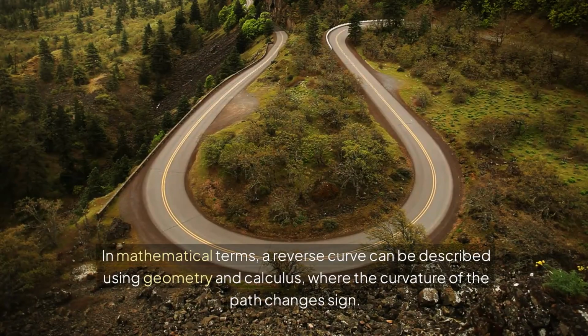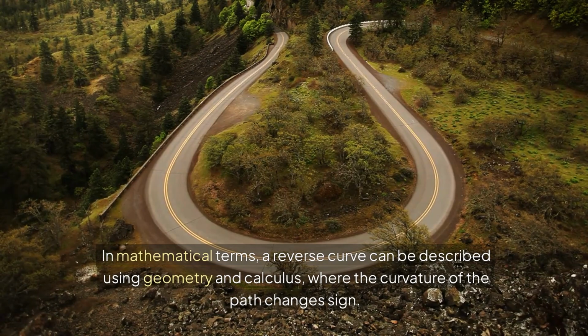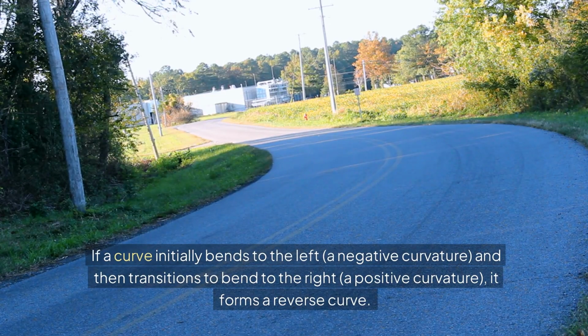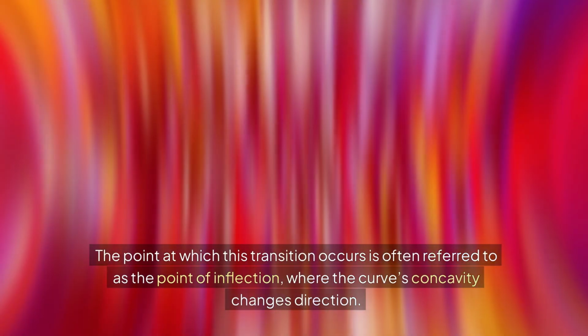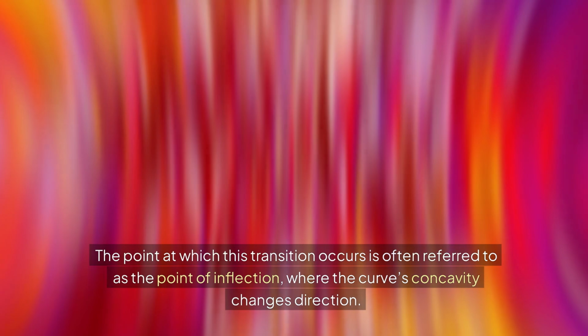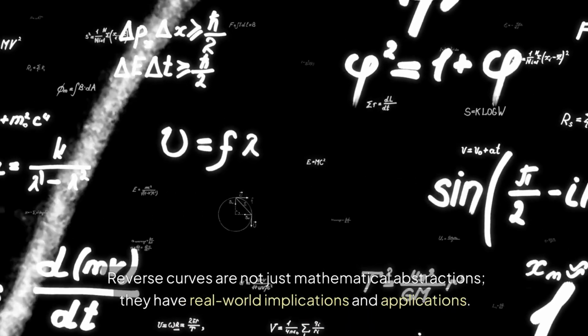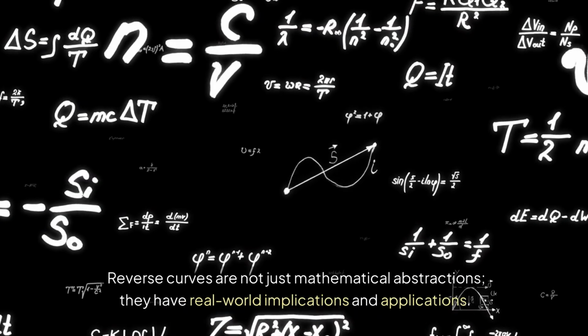In mathematical terms, a reverse curve can be described using geometry and calculus, where the curvature of the path changes sign. If a curve initially bends to the left, a negative curvature, and then transitions to bend to the right, a positive curvature, it forms a reverse curve. The point at which this transition occurs is often referred to as the point of inflection, where the curve's concavity changes direction.